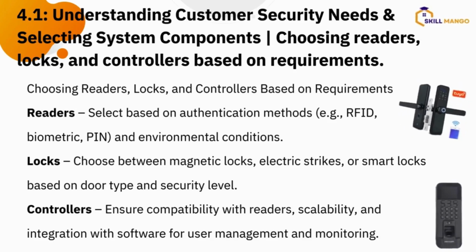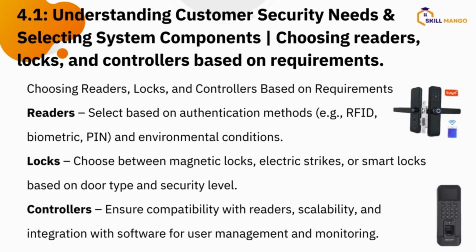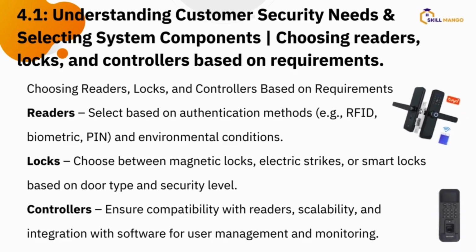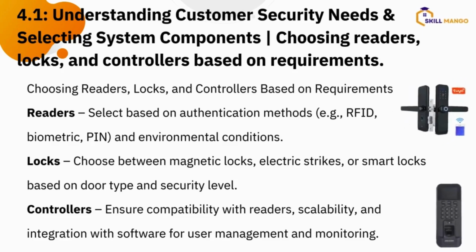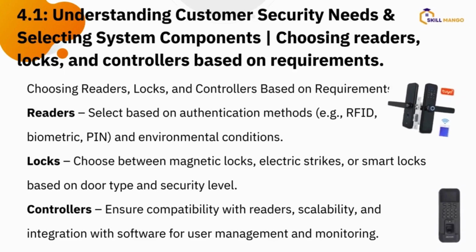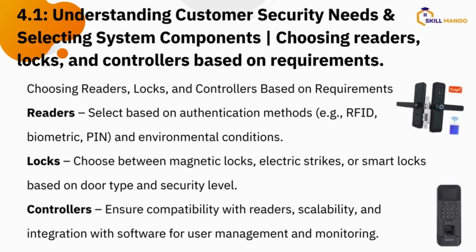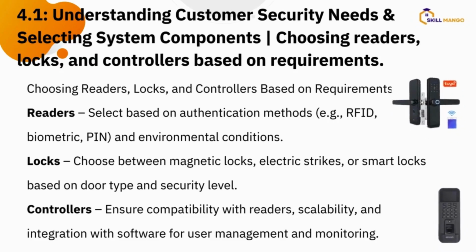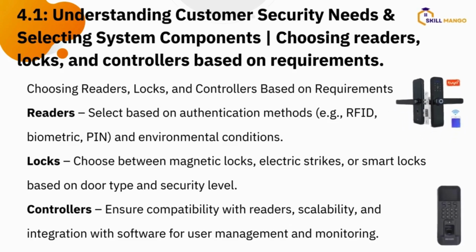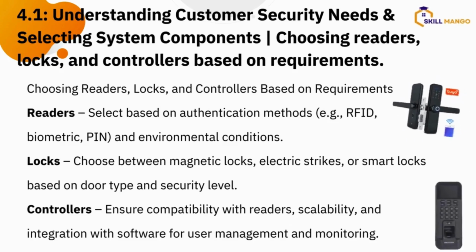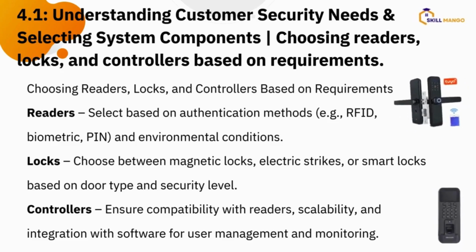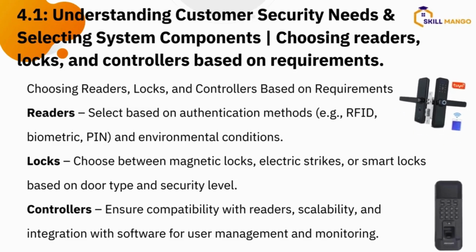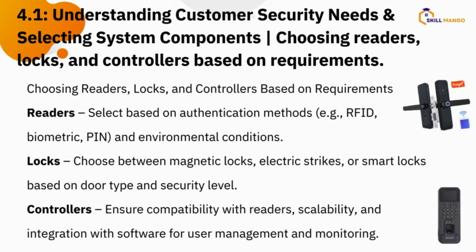But the electric strike does not work like that. With the electric strike, when they are locked together, even if power is out, they are locked. So whether there is power or no power, it is locked, as far as the system has told it to lock. The only thing that can tell it to unlock is the system. Either the reader or the exit button will tell it to unlock, and it will unlock. So that's the advantage of mag lock and electric strike.